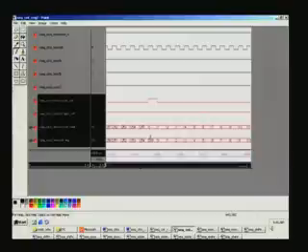When it is 255, this reset counter, which is a combinational circuit sensing counter edge equal to 255, happens right here, and immediately it goes high, being a combinational circuit, and remains so as long as it is 255. Once this is done, this will make the counter 0 on the following positive edge of the clock. That is what you see here, and thereafter it keeps on rolling around and increments from 0 onwards, because it is being reset here.